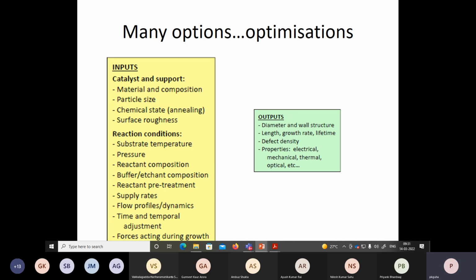Some prefer very high purity carbon nanotube, some prefer low temperature growth, some prefer defective carbon nanotube. For example, if you want to use carbon nanotube for sensing purposes, for example gas sensor, there you need carbon nanotube with defects, because in the defect places the gas molecule will attach. So those defect places will act as active sites for the gas molecule to attach. By defect I mean maybe some carbon atoms are missing, okay, so that is a defect, or some other material is attached to it, so that's basically defect or functionalization.